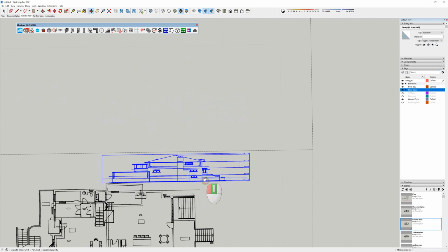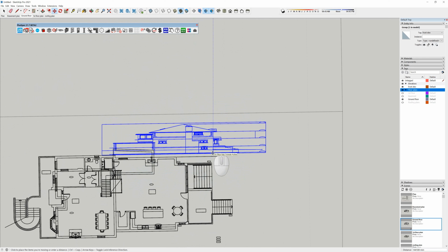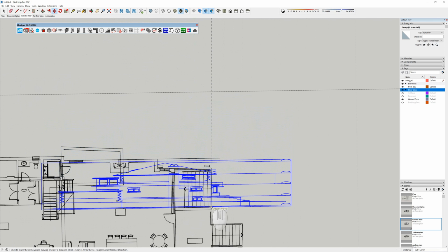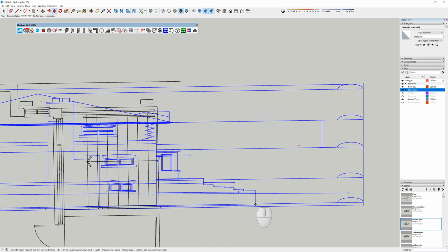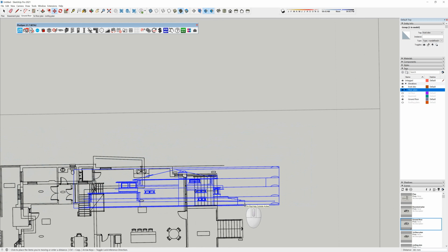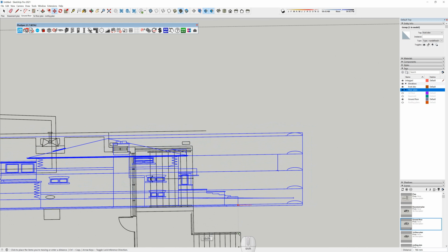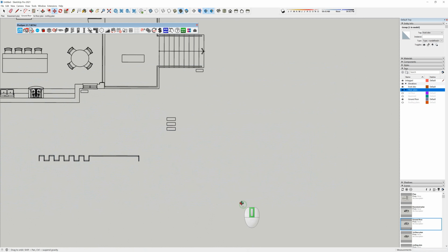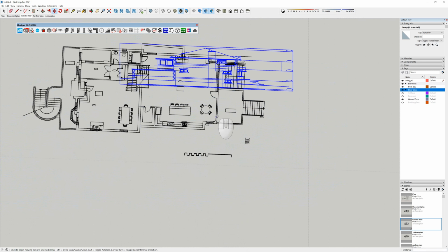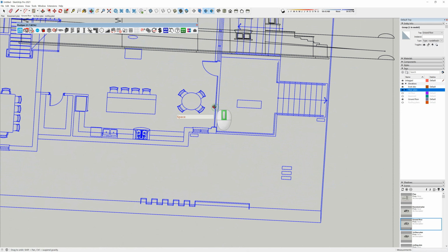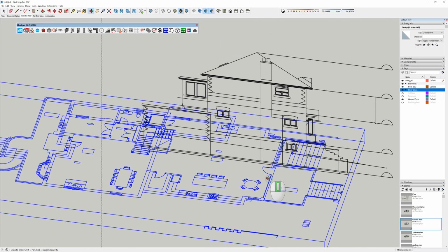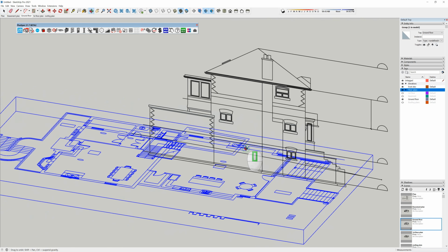And looks like the front of the stairs is going to be easiest for me. So I'm just going to place it here roughly at the moment, and then I'm going to go over and find the front of my stairs here, and you'll notice that I'm on a red axis. I could use my right arrow buttons if I chose. Go shift, and line that up with there. Okay, right. Really important when you're doing this to ensure that when you're using your orbit tool, which is the center mouse button, that you do it from geometry, because there's a lot going on behind what's going on here.